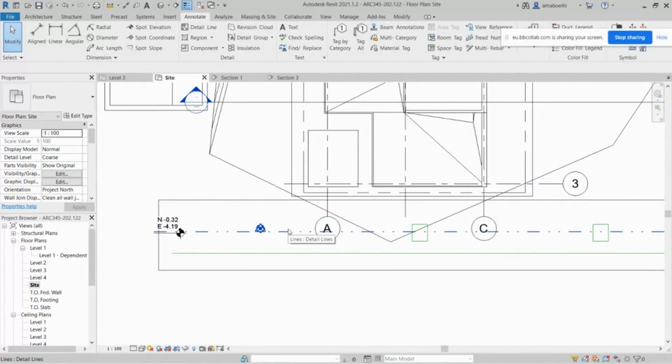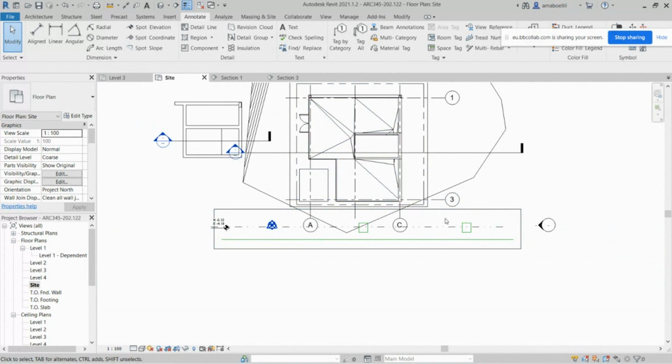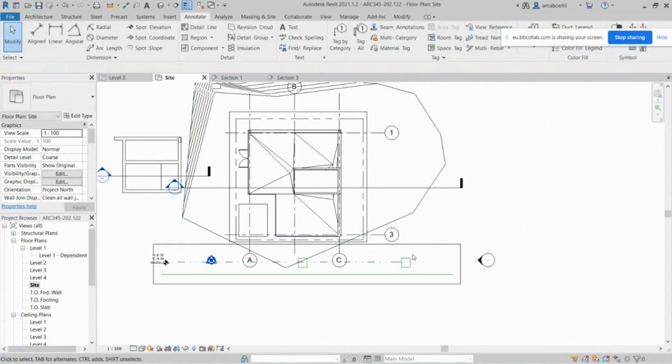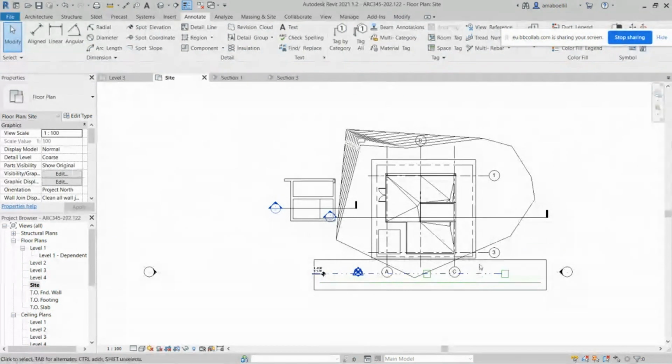So those are vital, and they have to be at least 30 meters apart from each other, and whenever there are elbows in the street. For instance, if this stops here and starts again going in that direction, you have to have a checkpoint here, which we call a manhole, so that a man can get inside and check. Whenever there are elbows in it, you have to make that. So you have to create these lines, and create them apart from each other. You can name them here, or you can create a legend and put them there. So this is what you need to build.